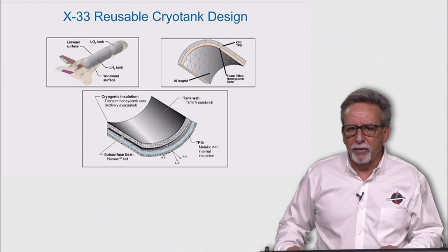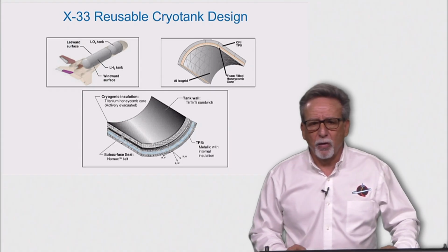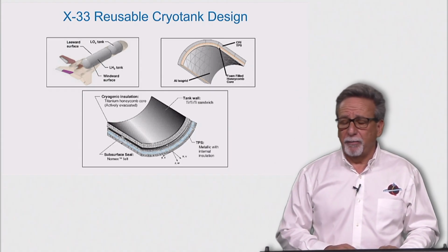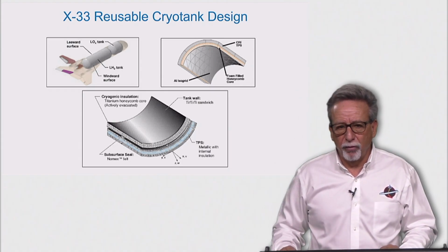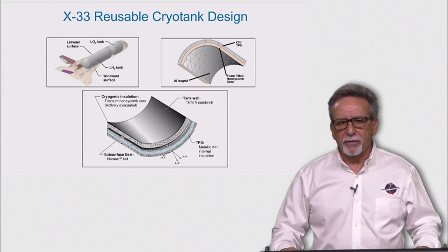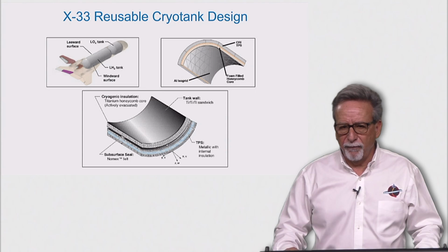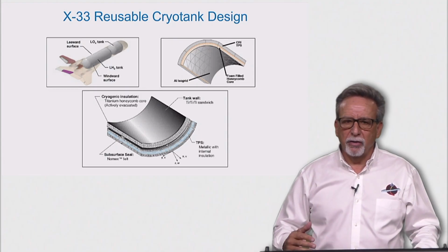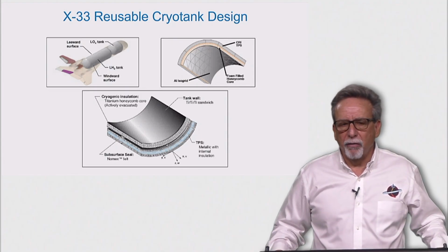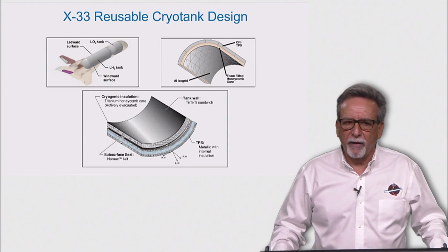One of the ideas uses a special titanium alloy for the face sheets and core that would not be susceptible to hydrogen embrittlement. The metallic TPS would have been a superalloy honeycomb outer face sheet, an efficient fibrous insulation in the middle, and a lower temperature material such as titanium in the inner surface, the honeycomb core, and also the inner face sheet.